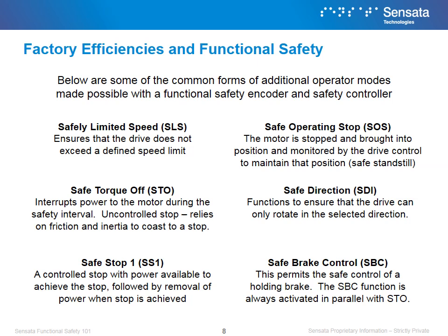Safe direction functions to ensure that the drive can only rotate in the selected direction. Safe brake control permits the safe controller of holding a brake. The safe brake control function is always activated in parallel with the STO, or safe torque off.